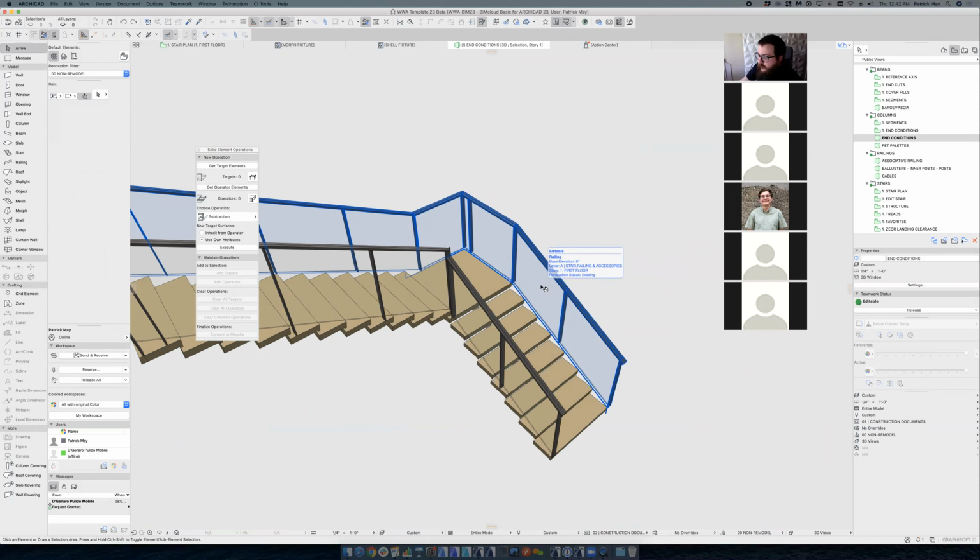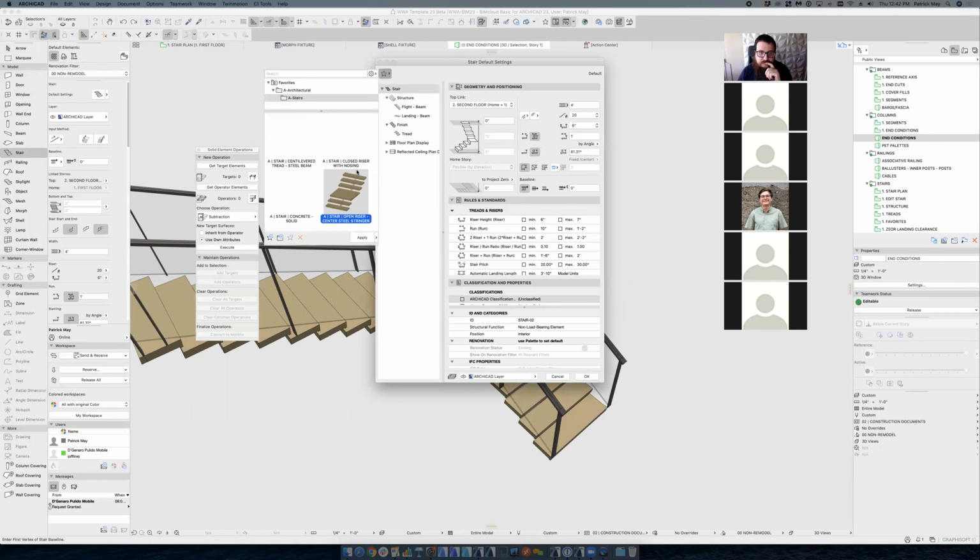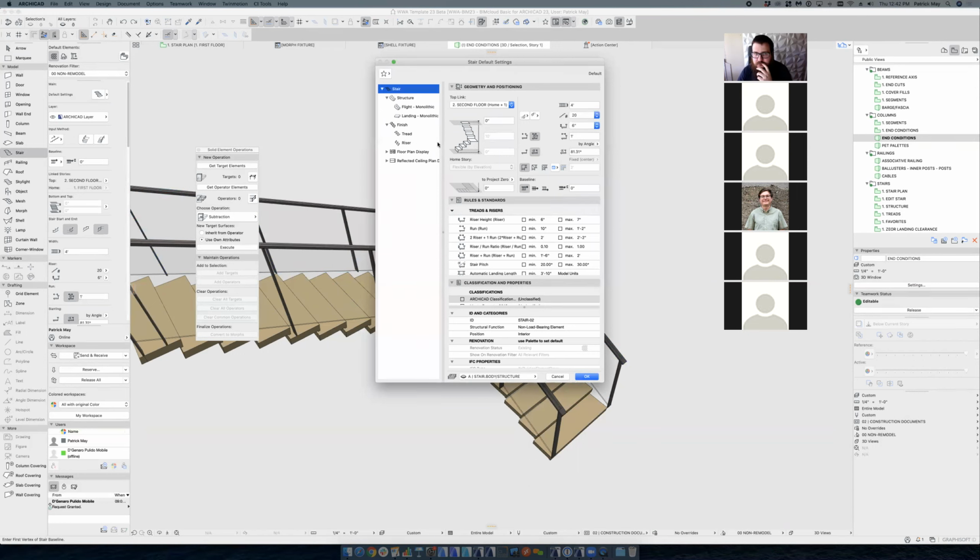I'll add that for stair modeling, it's something that I find myself doing: if I have to model stairs, at least at first, I might use the stair tool to help space out the risers and steps equally, and even add on the railings for how high that should be. But like Pat said, I always find myself eventually replacing that. But one good thing is if you let the stair tool do the math for you, it's a lot easier than trying to figure out the spacing on pen and paper. Then you can go ahead and trace that with your slab tool to draw every single tread.